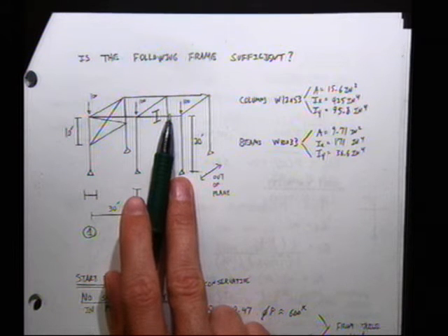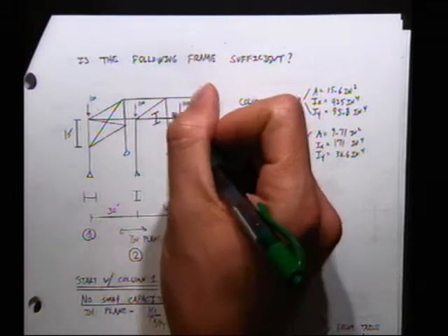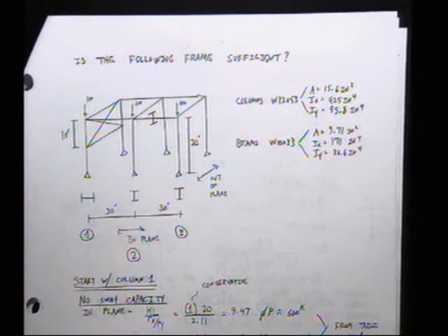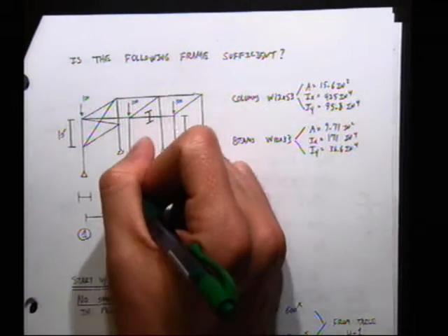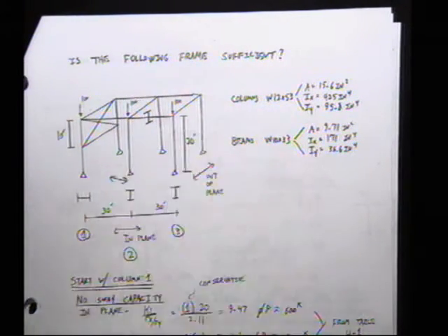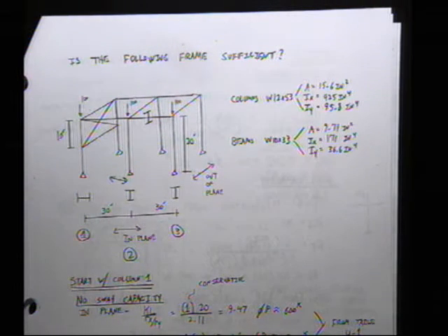The reason why is because if this material is extremely flexible, air for example, then if this frame wants to fail in this direction, the back frame doesn't help it. Let's say we have something very stiff in there, like concrete, a common flooring system.